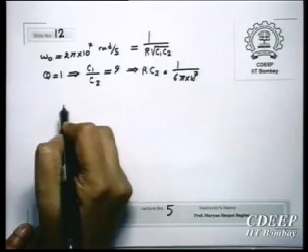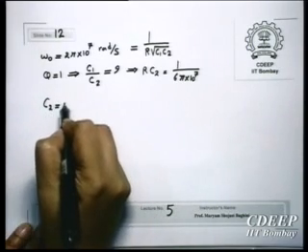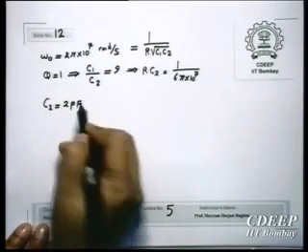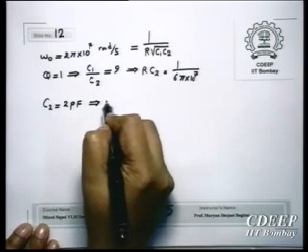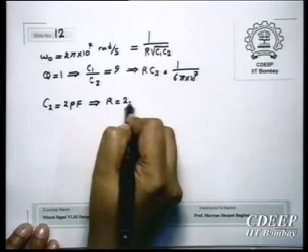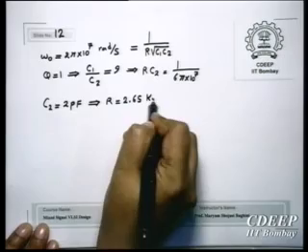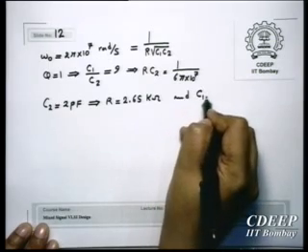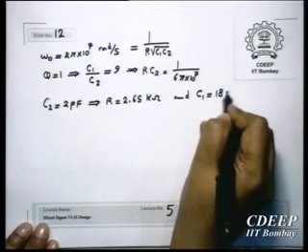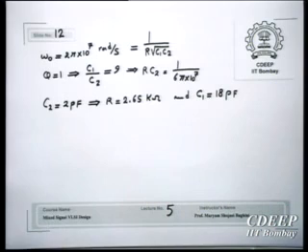So now if I choose for an implementation some proper value, suppose I choose C2 2 picofarad, R will be equal to 2.65 kilo ohm and C1 of course will be 9 times more, which is still okay, 18 picofarad.